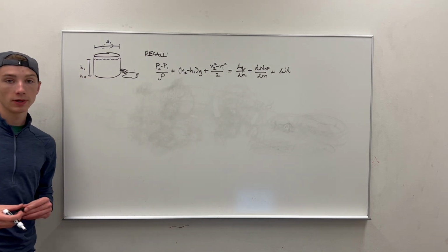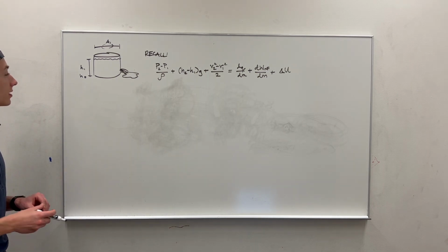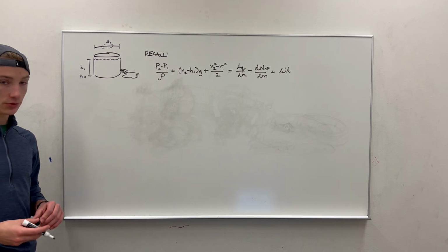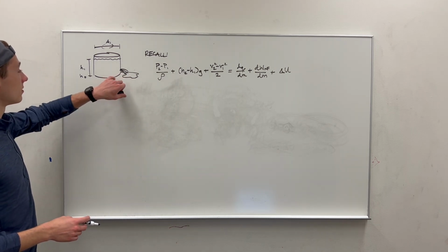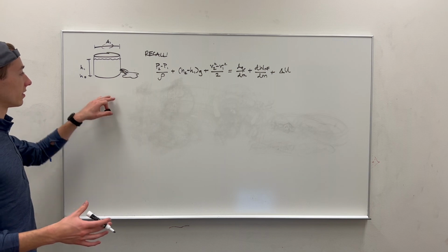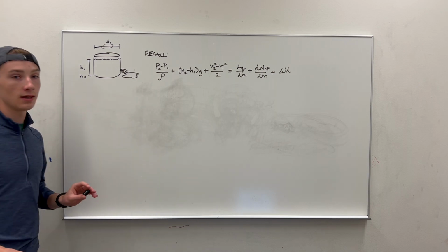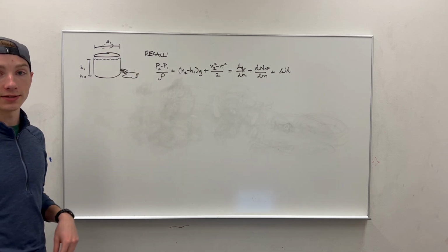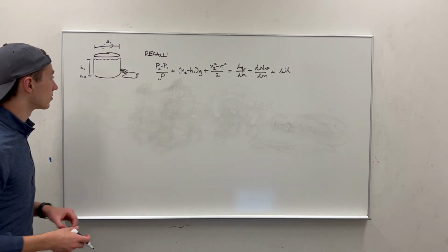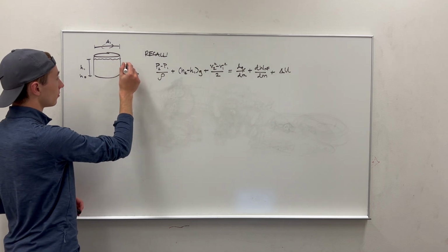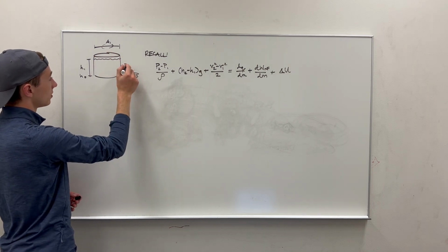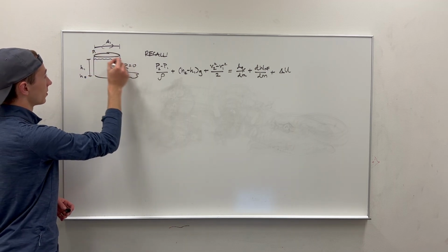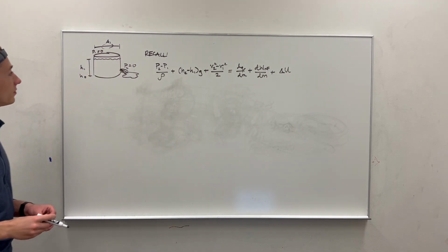And then we have to recognize that there is going to be a pressure at the top and bottom, and contrary to popular belief, both the pressures are the same. There's very little difference here. The reason being is because they're both exposed to the atmosphere at the top and the bottom. It's an open air tank in our situation, okay? So the pressure here, we'll still label, we'll give it pressure 2 and pressure 1. But they're both equal to atmospheric pressure, gauge pressure 0, okay?